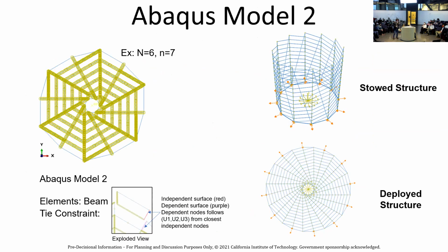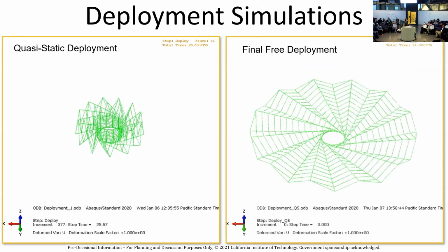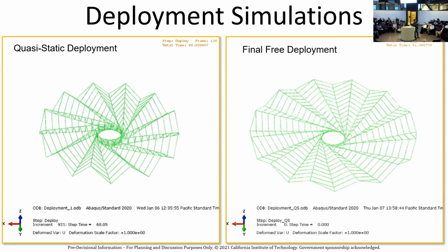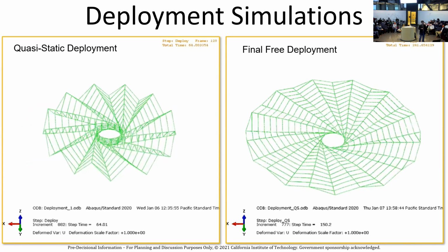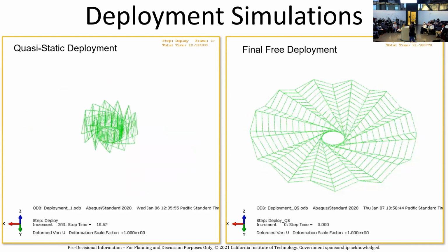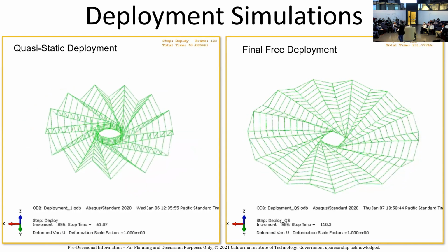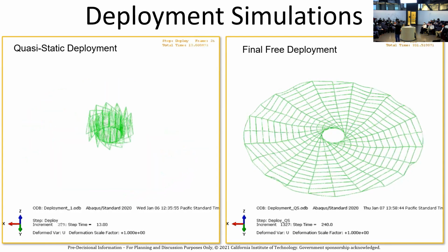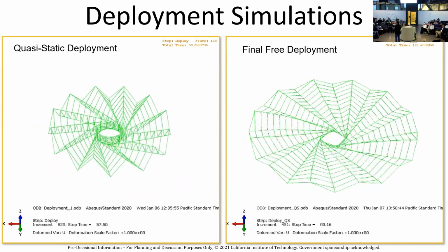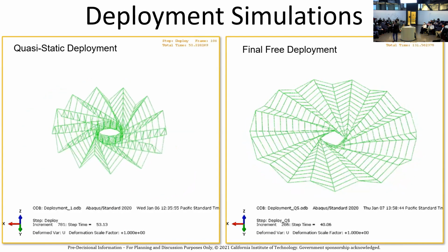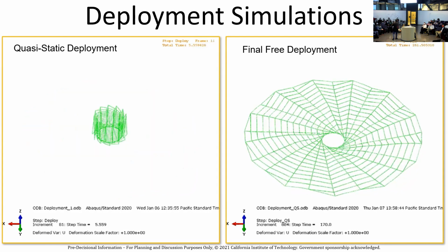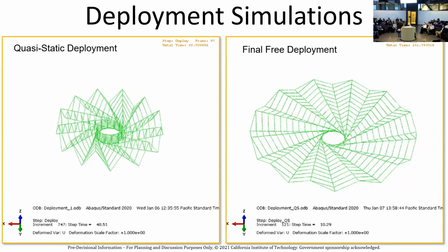Again, this is our Abaqus model. For those of you who are interested in FEM, we're using a different model for this. Again, the same pipeline shown previously. On the left-hand side, you can see the fold pattern that we just talked of. There's an interesting thing we discovered when we started using this fold pattern: it is bistable. That means you first keep applying force and the fold pattern opens up, but only to about 90%, or actually 92%. And then for the last 8%, the pattern opens up on its own because it crosses a bistability, and the open configuration is the preferred configuration.